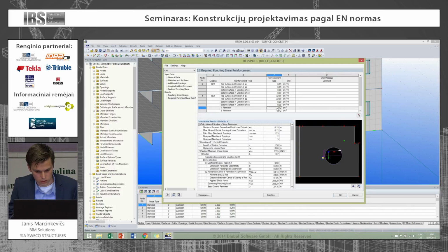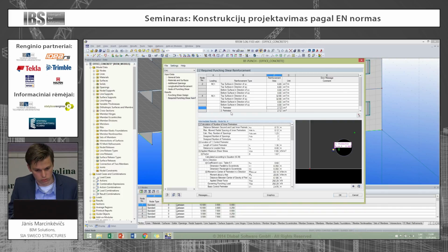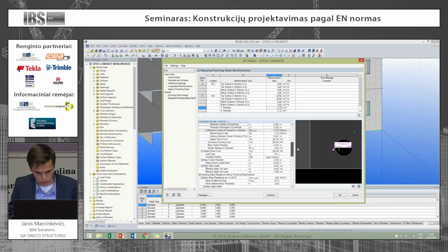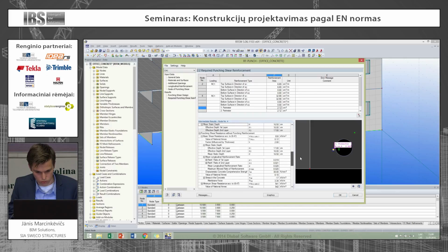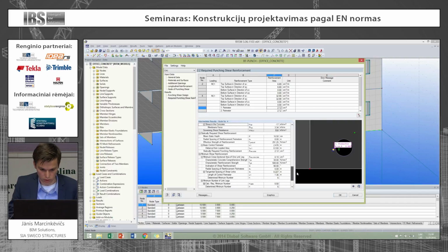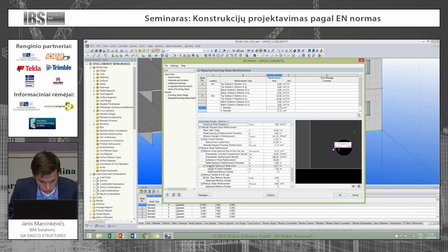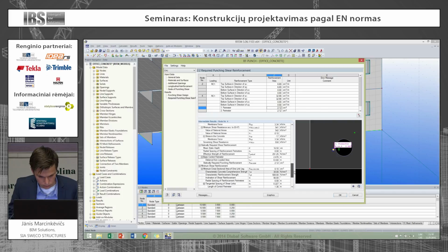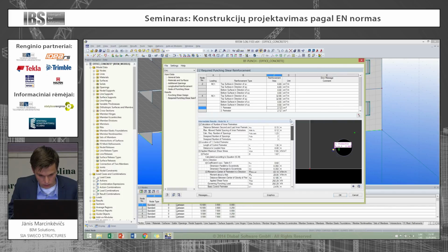As I said, there you don't need any. And on the second one near the opening, you need some shear reinforcement, and it should be divided into perimeters. And there is also information how you should put those links. There is a tangential spacing of shear links, diameter, and the number of the shear links that you need. So I guess anyone who has been calculating the punching will appreciate that it's quite simple and straightforward.